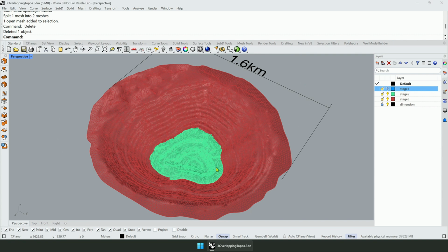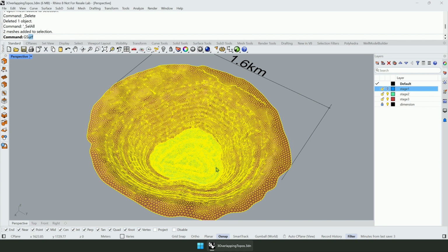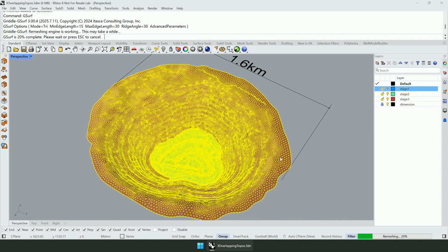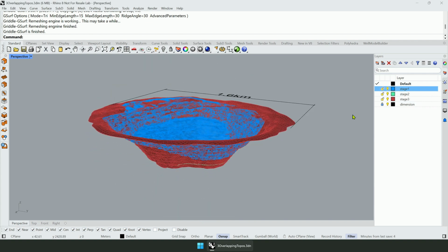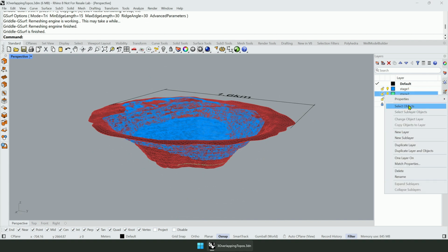It's very important to remesh after gCollapse, because we did automatic intersection, and automatic intersection quite often produces very thin, sometimes even sliver-like faces. So let's remesh these 2 meshes using these parameters to replicate the original mesh element size. So this will clean up meshes after the initial gCollapse, and will allow us to use this base mesh again for the next collapse stage.